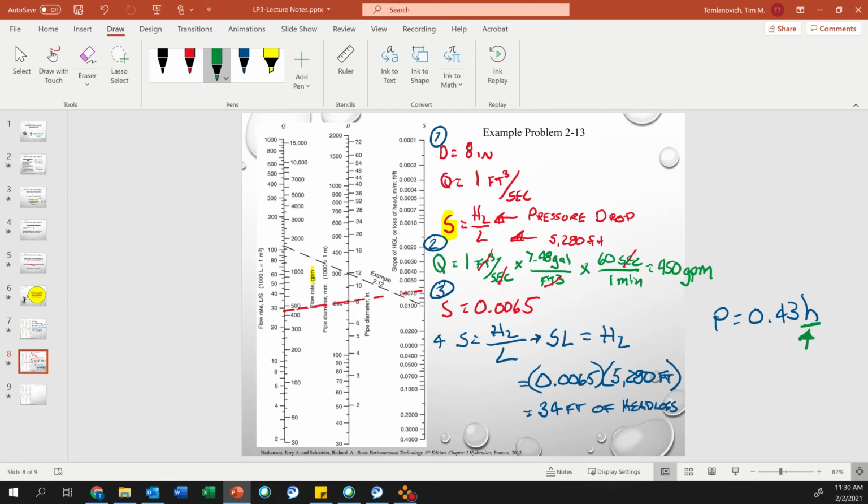So with Hazen-Williams, we can calculate how much pressure we're losing per mile of that 8-inch diameter pipe based on this coefficient of 100. So if your house is a mile away, we're losing 15 psi. That's part of waterline design.